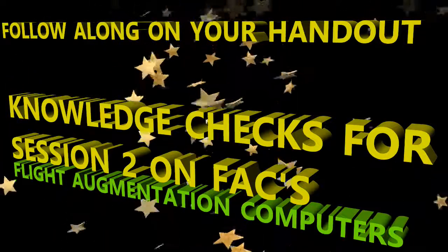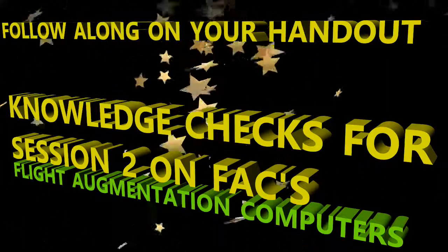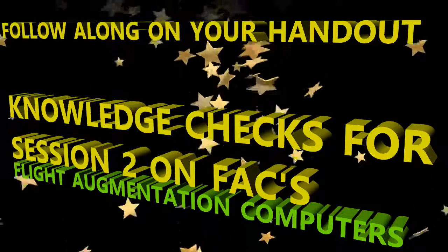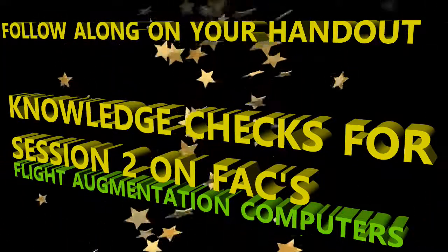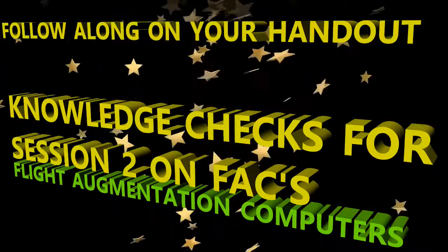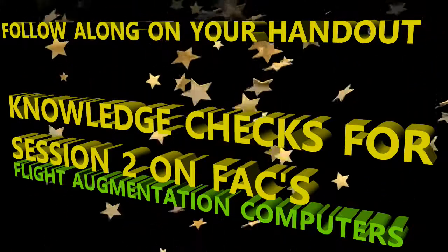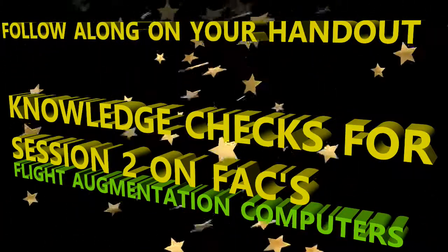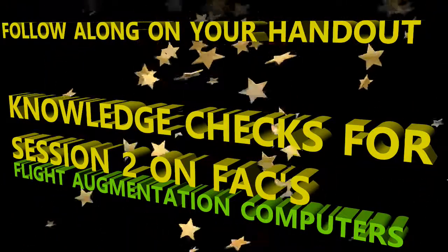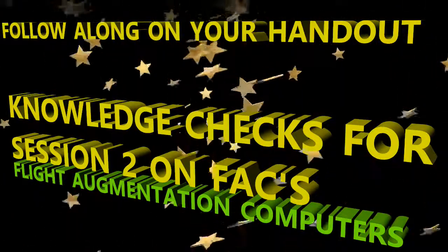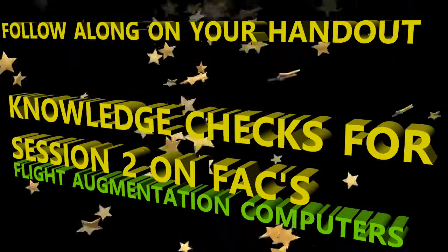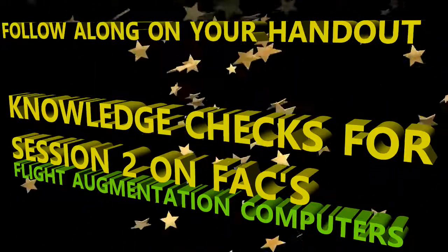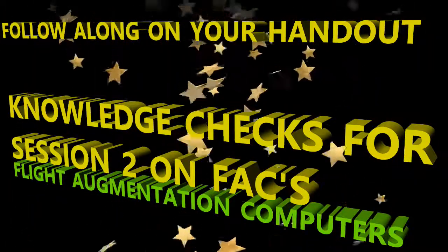From which computers does the FAC receive data in order to calculate flight envelope protection? Is it the first one: LGCIU, ADIRU, FMGC, and SFCC, or the ELAC, FADEC, and SEC? Okay, it's going to be the first answer. All of those different computers.